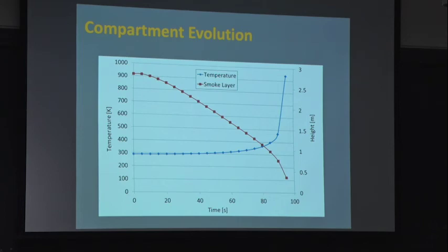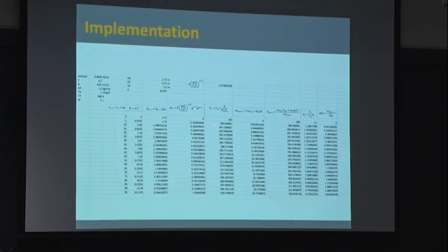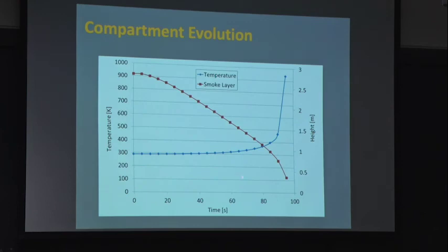Is that okay? Now obviously, when I get close to the surface, my entrainment correlation doesn't work anymore, because it was not designed to have a smoke layer right on top of it, so the whole thing breaks apart. And this very simplistic approach of two control volumes that are exchanging mass and energy doesn't work anymore. So if at the end the height goes to 0, then the mass of air entrainment goes to 0, and the temperature will go to infinity. Okay, so it's going to break down.